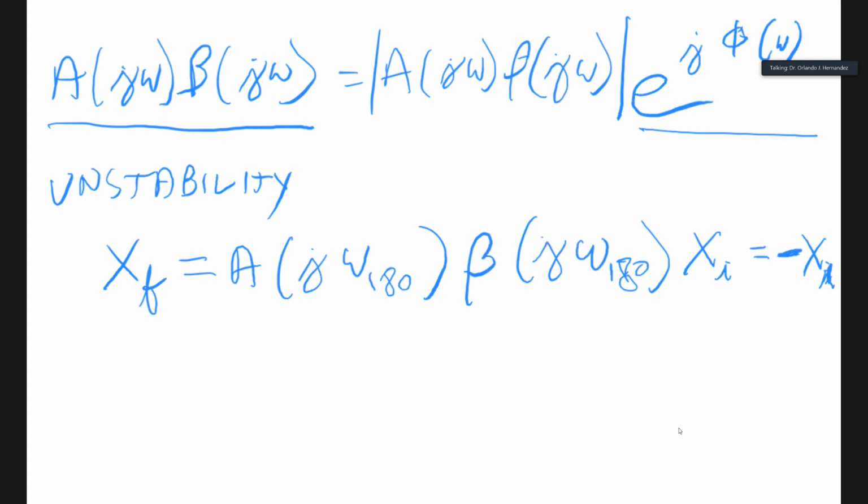At that specific frequency, essentially, the system will oscillate. It will be marginally stable in the sense that it will oscillate, but it will not be unbounded. Oscillators are useful, and that specific condition you may want to sustain and control, and that can be a useful circuit.